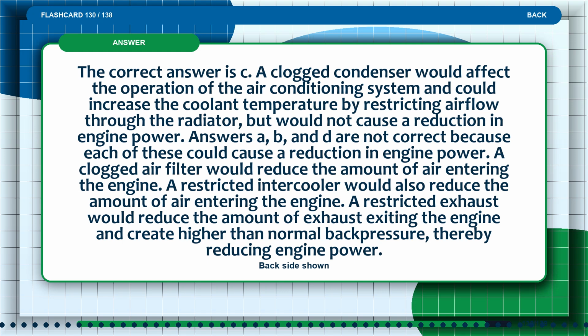The correct answer is C. A clogged condenser would affect the operation of the air conditioning system and could increase the coolant temperature by restricting airflow through the radiator, but would not cause a reduction in engine power. Answers A, B, and D are not correct because each of these could cause a reduction in engine power.